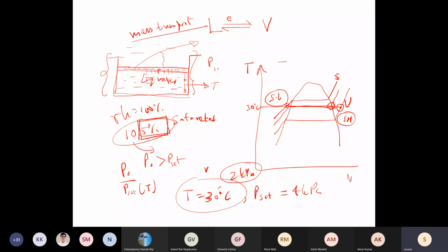Okay, but of course, you know from fluid mechanics, you can have drag forces on that liquid droplet. It can still hang in air. That is what you see in foggy weather, which is basically liquid droplets hanging in air. But when we are making the psychrometry chart and discussing psychrometric processes, we will not discuss the misty or foggy situation. So you will always be limited to RH equals 100%. RH equals 110%, 120% means that you have liquid droplets hanging in air.